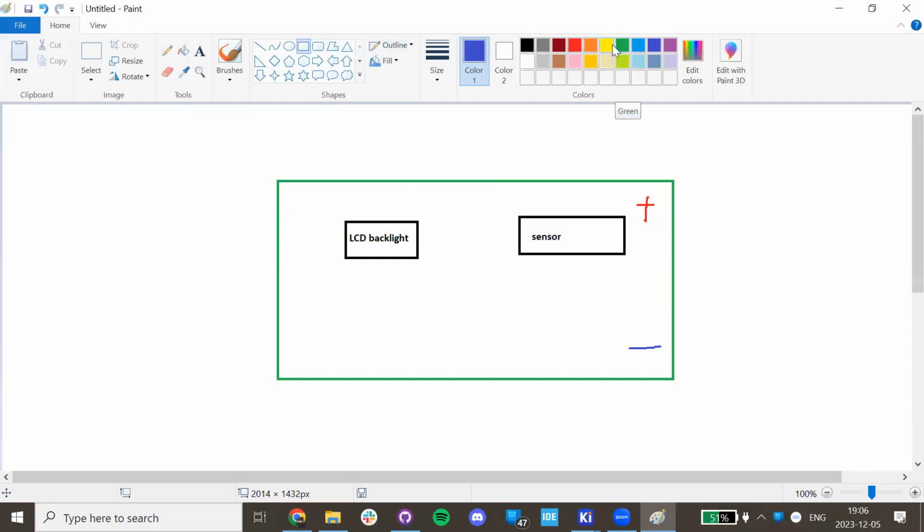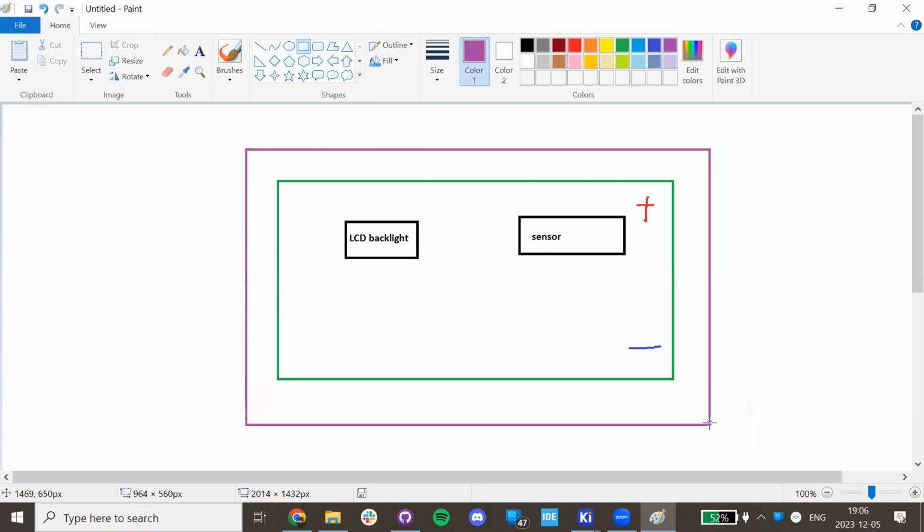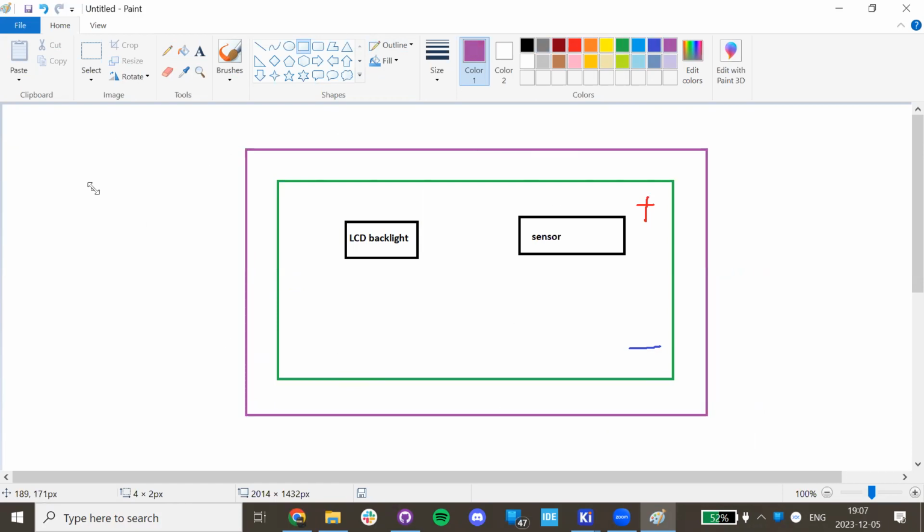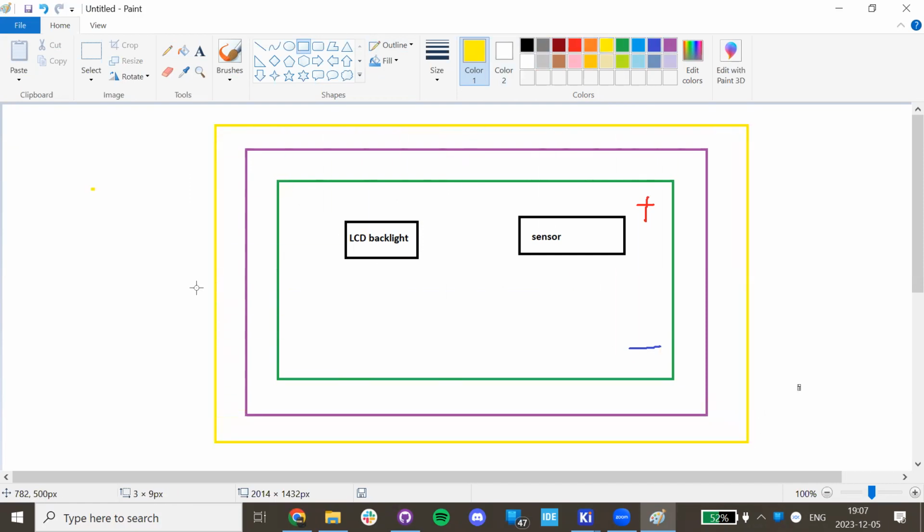This varies with how complex your PCB is, but in the beginning, what you want to do is create a layer on the front of the PCB here. It's just adding copper, you could say, a possibility to etch out this copper. And then on the backside of the PCB, so you have some prepreg or FR4, some isolated material in between, we add another layer. This is just so that we know that there is a layer there. This will make sense why I'm doing it like this. We're just saying that we have 2 layers here.